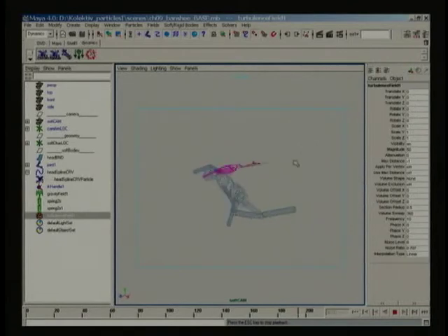One thing I always try and avoid is crossing expressions over from the scene universe to the particle universe. Maya uses different engines to calculate regular expressions and particle expressions, and using the regular engine to query a per particle attribute can slow down your scene's playback.